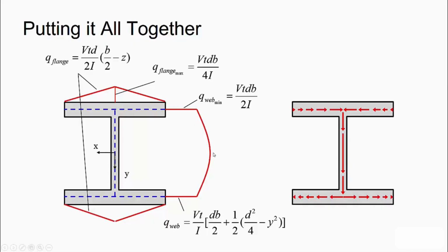And then finally, our maximum shear flow is always at the neutral axis. If you recall how we derived the shear formula, that should make sense, because if you do the section at the neutral axis, it's right at the point where the normal stress due to bending switches from compression to tension. And so sectioning it there will get you the maximum amount of normal stress in the same direction to be balanced by the shear flow or shear stress.